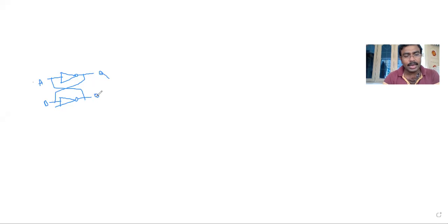Remember, I told you that after expanding this 1-bit memory cell, it has some limitations: it can only work with a single input. It is impossible to give both the inputs at a time. That is one limitation it has. And a few observations we have to take from this one, guys. What are the few observations? We can give input and get output at the same time, and we have 2 outputs Q and Q bar, which are inversions of each other.